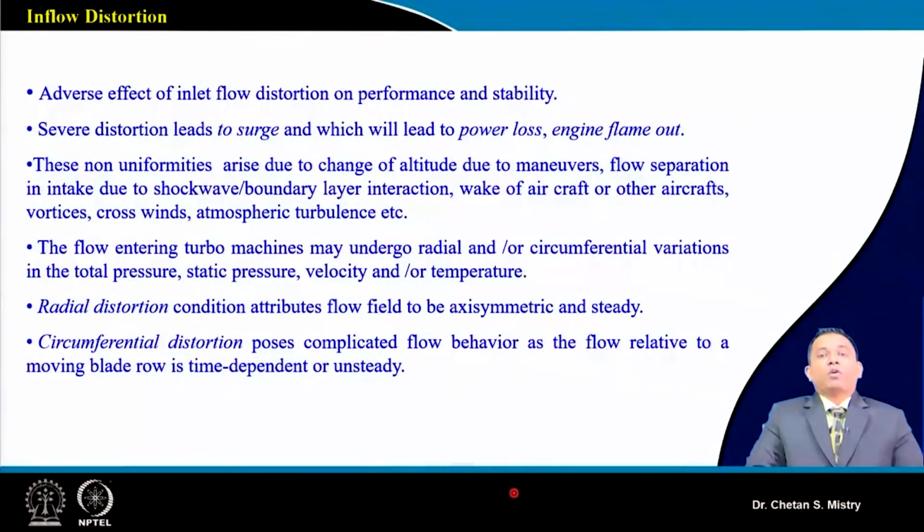When we are talking about radial inflow distortion, this is axisymmetric and steady. It is not that serious. But when we are talking about circumferential distortion, that is where we will have flow which is in relation to the moving blade, and that is a time dependent or unsteady phenomenon.